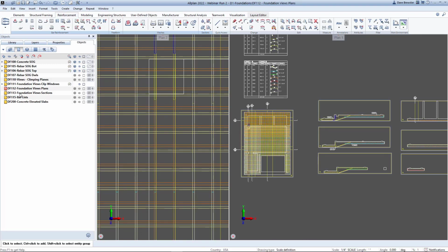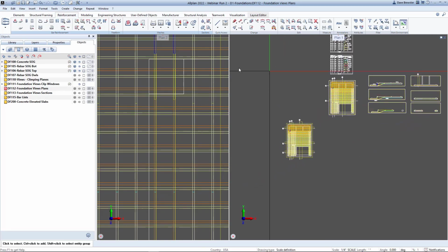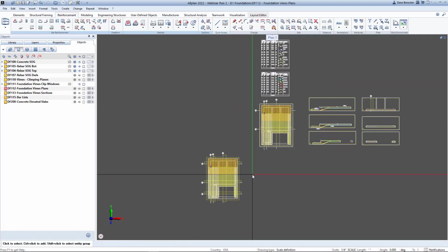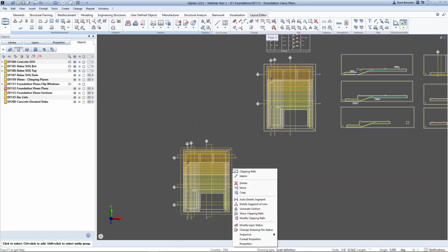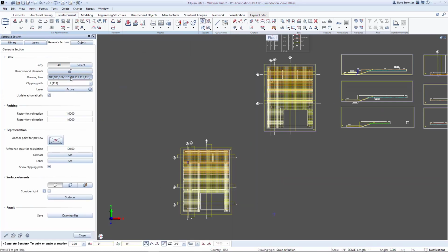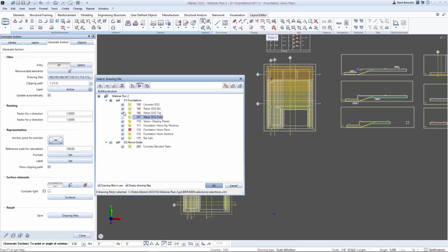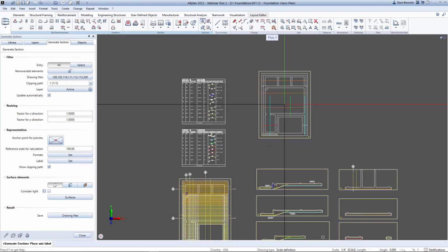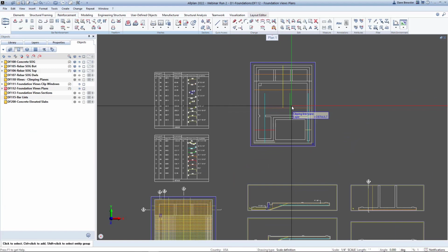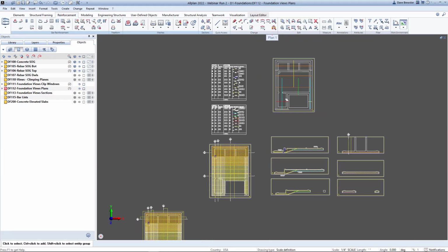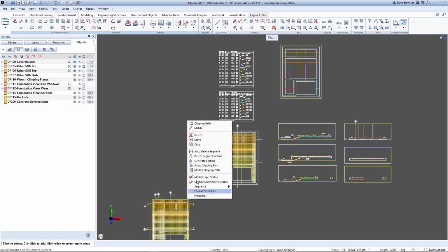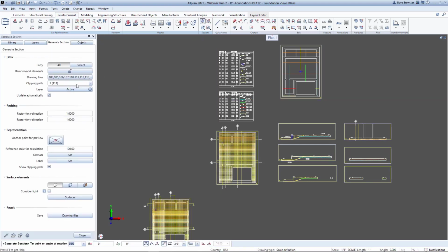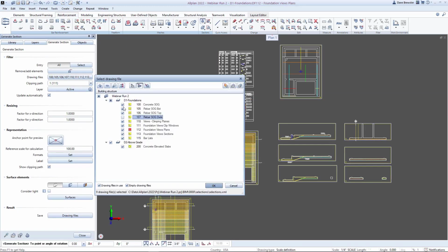So with that, we're going to change to another drawing file, and this one we're going to pop on our plan views of the objects themselves. And we go to a single view here. I'm going to generate a section. I right click on here, go generate a section and pick the drawing files. I only want to show the bottom bars in this one. As I pop it in, you notice it's going to pop in just single placements of the bars. All the bars are there, but it's only going to show me one bar for each bar set that exists.